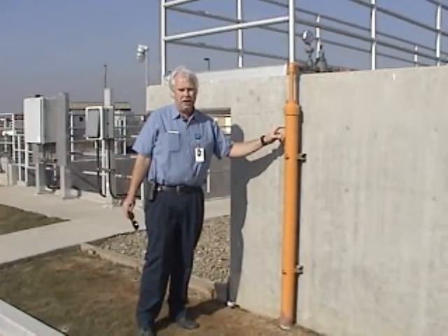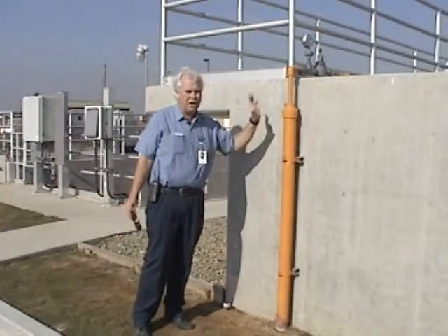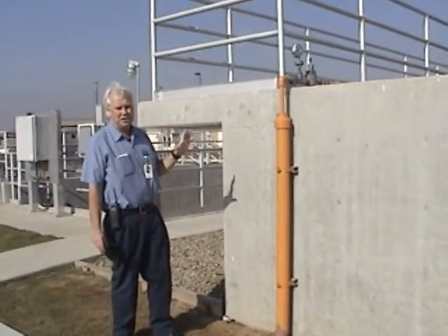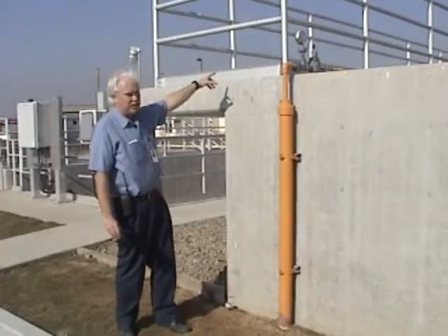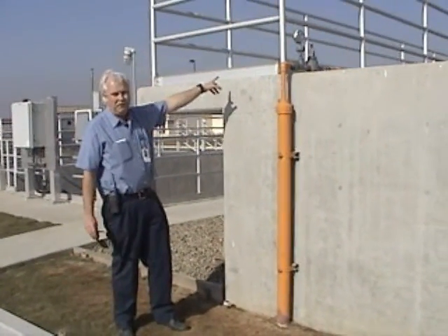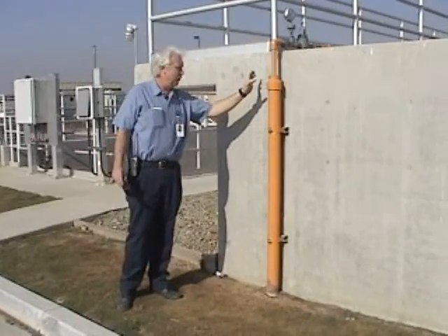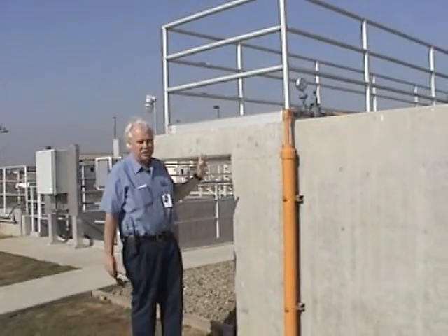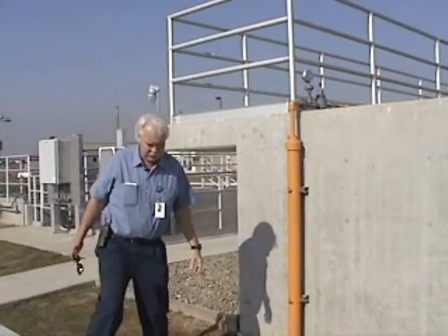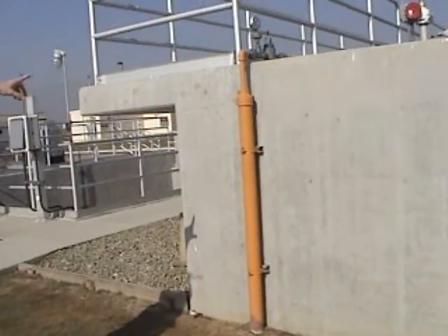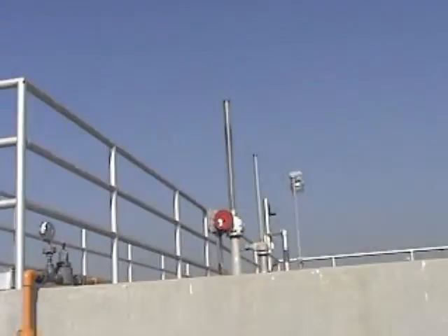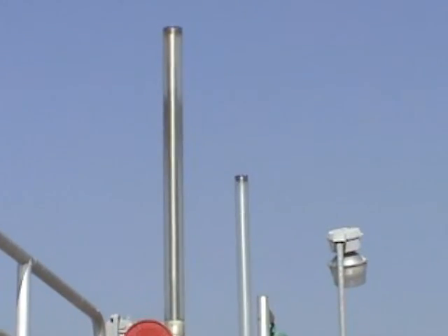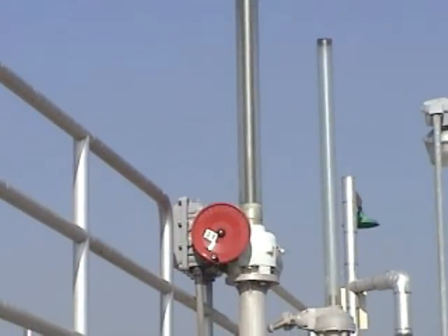We can set the gate up to close on a positive chlorine residual seen at the outfall Z-chlor. The thing is, it's going to go positive on the outfall Z-chlor, but the gate takes 6 minutes to close. Our limit is 5. So we're probably going to have a violation if you're on this dechlorination system and you have a problem with it. Even though the gate's going to close, it's not going to be fast enough. One of the things I'm looking at doing is running that gate halfway down, so that if it were positioned lower, it would close quicker and maybe catch it before we had a problem.